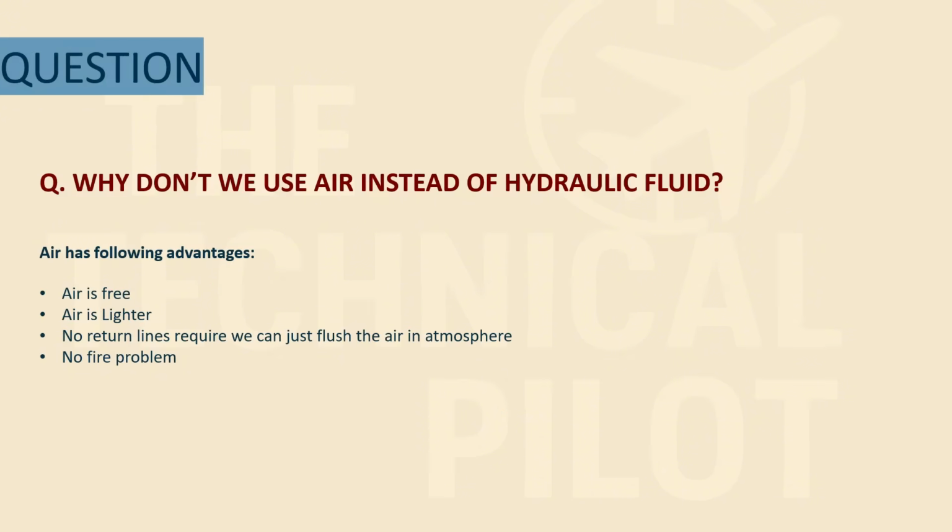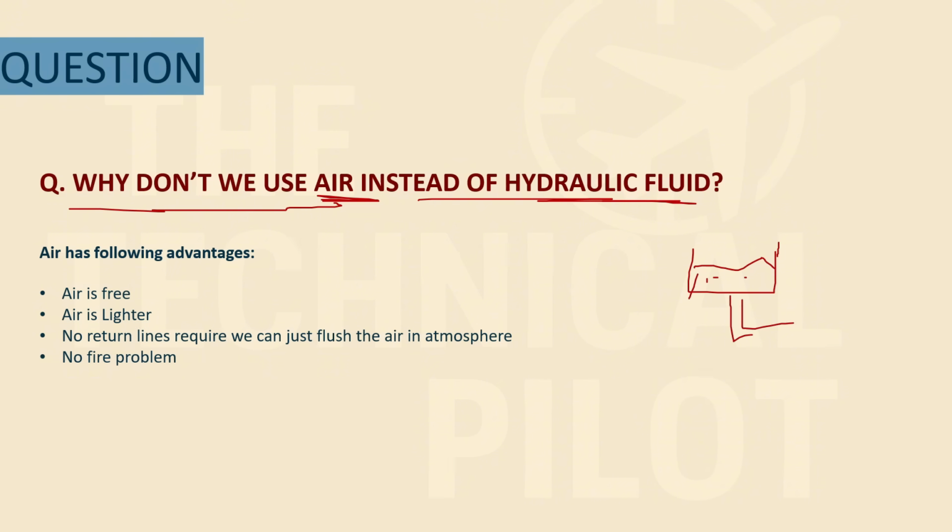And there is this question: why don't we use air instead of hydraulic fluid? When you are using a hydraulic fluid where you are storing the fluid in a reservoir, there is a problem of leakages, there is a problem of it catching fire, there are problems where the hydraulic fluid might create foaming, or there are a lot of problems, right? So why don't we use air? Air is in fact free. It is lighter than fluid, obviously, and it does not even require return lines.